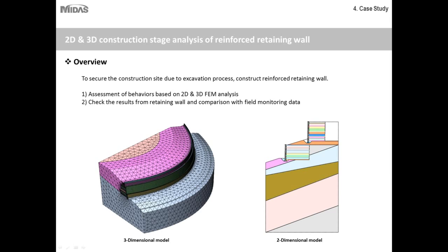So they have to consider the stresses that would be occurring in the wall members along this arc line. They had no option but to have a 3D analysis model. Had this been a relatively straighter wall, then 2D analysis would have been sufficient, and this enabled them to obtain the relative displacement of the soil strata along the periphery of the wall.